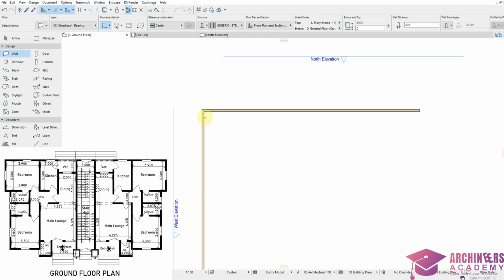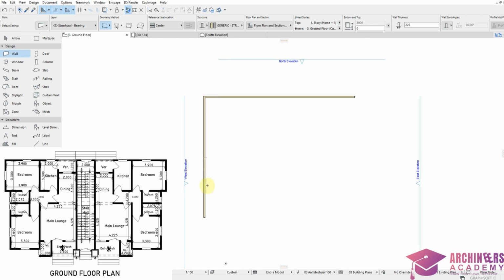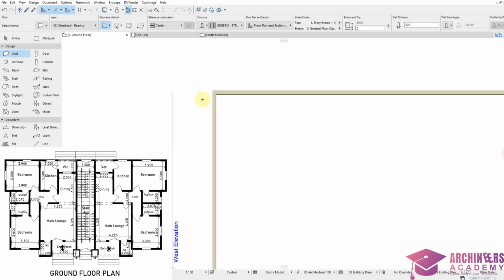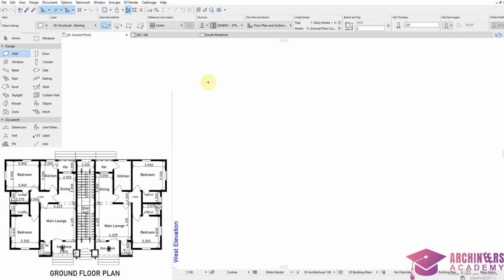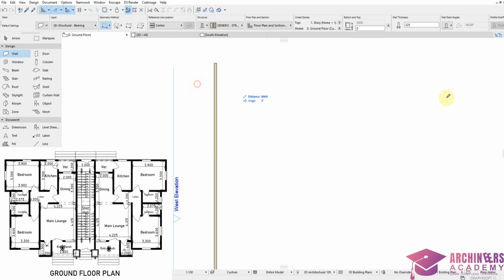If you want to learn how to change it more frequently, you can go back to our previous videos on wall and wall settings. Then you saw what I did. I drew a vertical line and a horizontal line. This is how I start my drawings. I only create new walls. Just see what I do again. I've clicked on wall, I've clicked OK to the settings. Now this is the wall settings. I draw a vertical line and I draw a horizontal line.